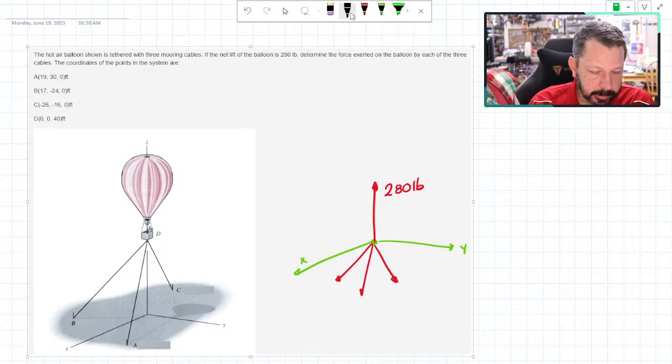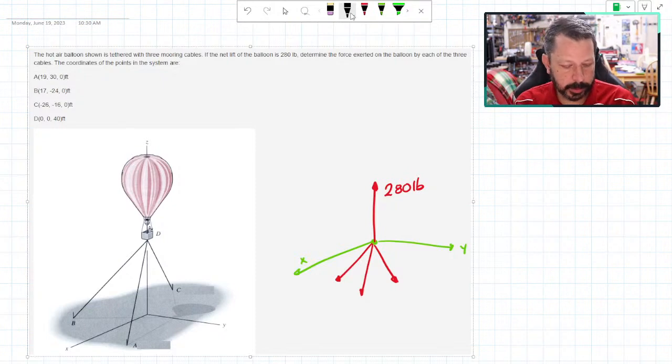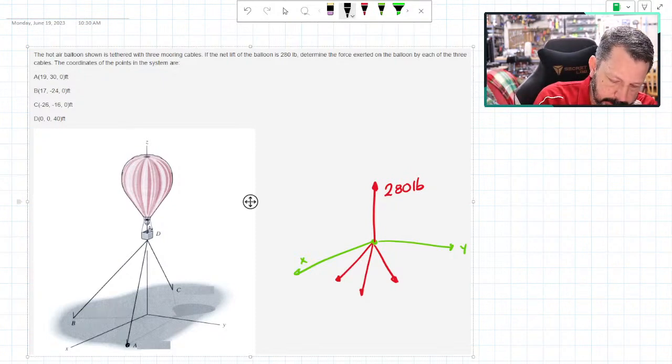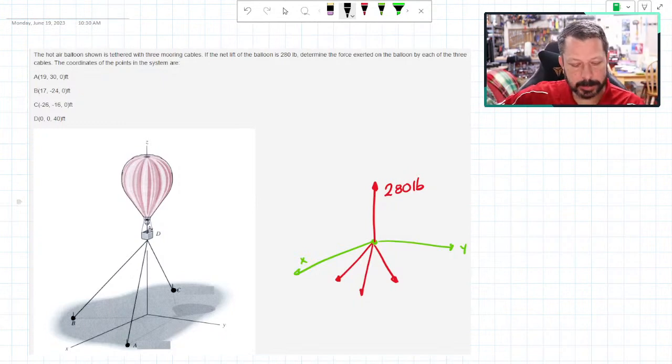So that's fine. And then they are showing the coordinates of these individual points on the ground plane, which is the XY plane that they have. So we basically need to subtract 40 off of these points because we're moving our XYZ coordinate origin up 40 feet.